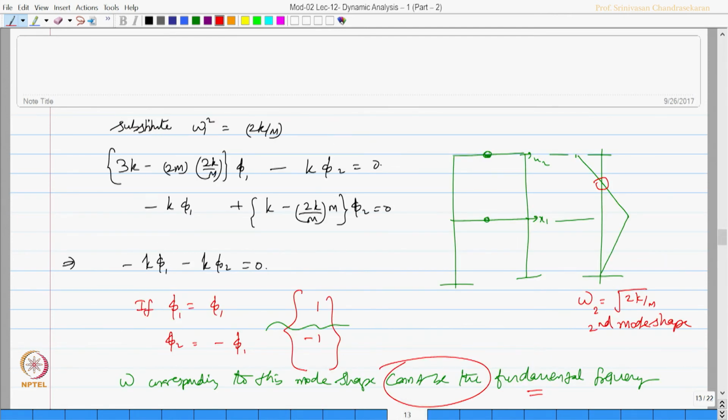So, we found the mode shape, we got the characteristic, there is no 0 crossing, then we can say first frequency. If there is 1 crossing, then second frequency. It means 0 crossing will be of 1 order lesser than the frequency. So, if it is second frequency, 1 0 crossing, third frequency 2 0 crossing, first frequency no 0 crossing. So, we should work out the first frequency.